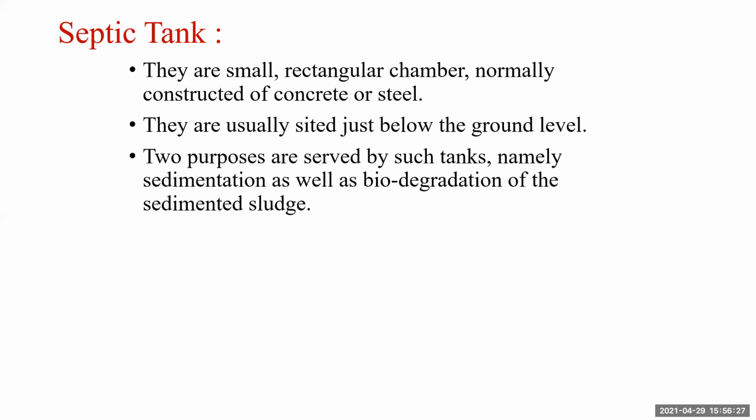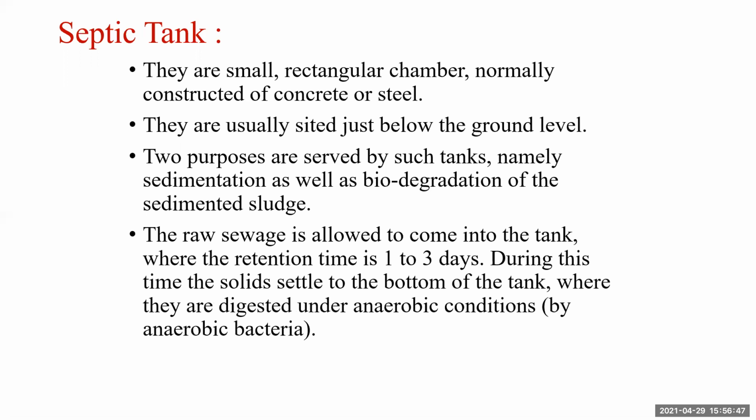So small rectangular chambers, normally made of concrete or steel, usually sited just below ground level. The tanks serve two purposes. First, sedimentation, as well as biodegradation or oxidation of the sedimented sludge. Raw sewage, after pre-aeration or directly, is allowed to come into the septic tank, where the retention time is 1 to 3 days.